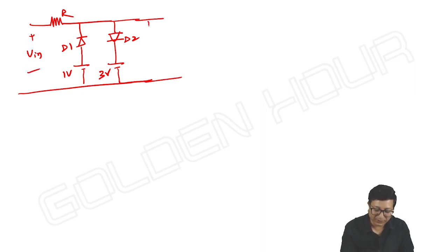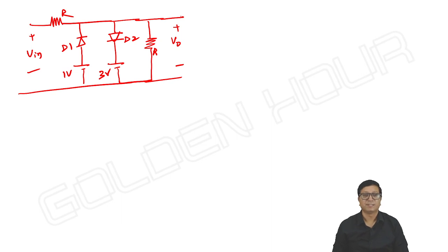In this circuit, suppose one more resistor is connected. Maybe 1K, both the resistors maybe 1K or 5K or 10K, something like this. Then how do we do this? Okay. Take the three possible cases. First, D1 is on for input less than breakpoint 1. D1 and D2 off, above breakpoint 1 and below breakpoint 2. Next, above breakpoint 2, D1 off, D2 on. These three cases as usual.